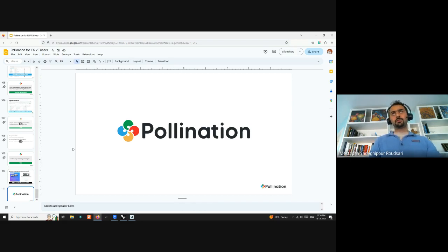For Revit, we support from Revit 2019 to 2024. Maybe not 2019, but yes, all of that. You can do Rhino 6 too, actually, but if you have Rhino 7, it will be easier. With Rhino 6, you have to open it 3 times because of how it loads the DLLs, and we should be supporting Rhino 8 as Rhino will be released soon. Okay.